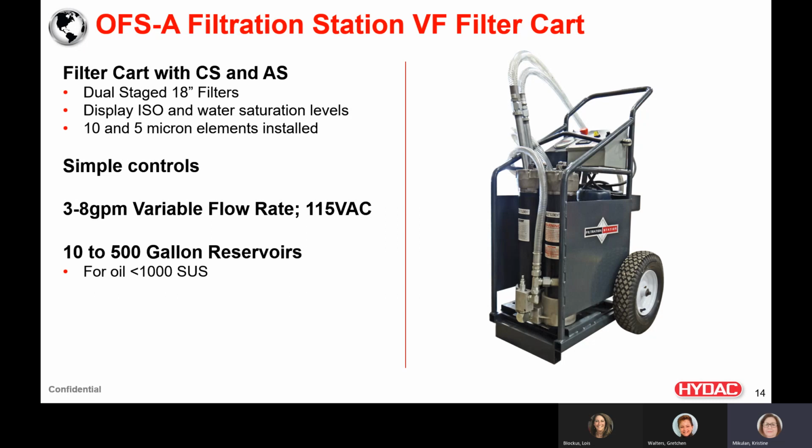This is our filter cart with an onboard particle counter and water saturation sensor to display both the ISO and water saturation levels of the hydraulic oil. It has two 18-inch filter elements in series, or stage filtration, with a 10 and 5 micron element installed in the filter housings.